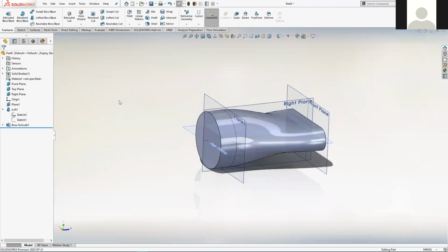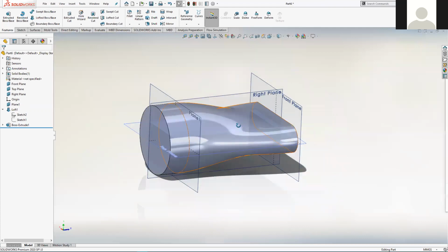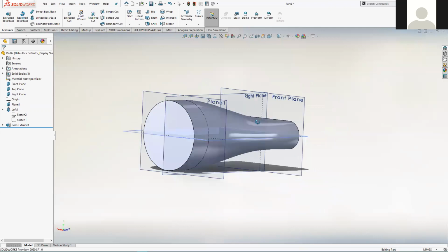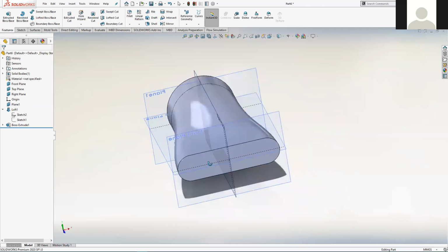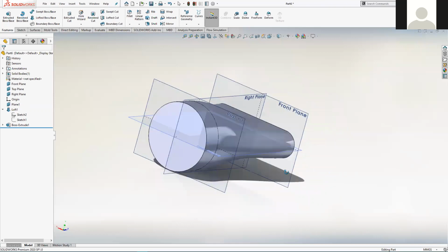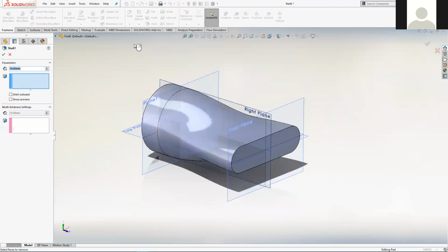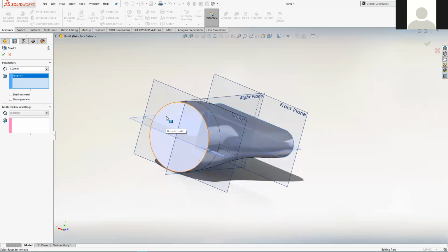So there's 2 other features here. The first one is, because these are made out of sheet metal, formed sheet metal, they have a thin wall to them. You can see that we've modeled ours up as a solid block that isn't hollow at the moment. So we need to hollow it out, which is the shell feature, which I'm sure we used a few weeks ago. In the shell feature, you tell the system how thick you want the walls to be. So I think we'll just have 1 mil. And then you click on any faces that you want to get rid of entirely. So in our case, it's that end face and that back face.